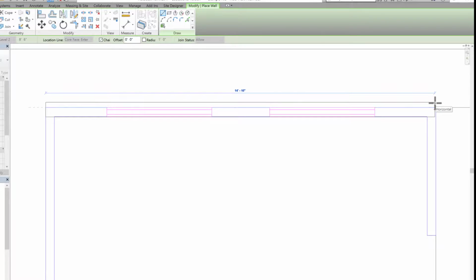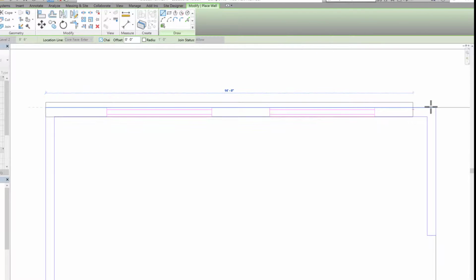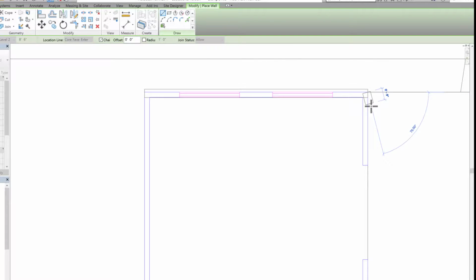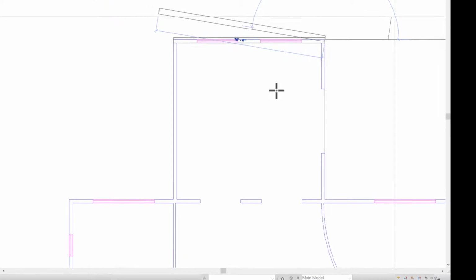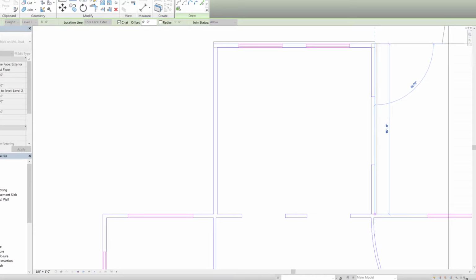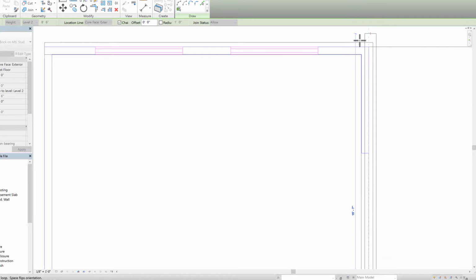So let's do that, because the chain option is checked here. When you will be drawing, if I draw this wall, let's say, and if I click here, it will make a chain. It will continue that wall. So make sure this chain option is open when you're drawing this wall. So I'll go ahead and click here, and as you can see, it has already finished this corner.